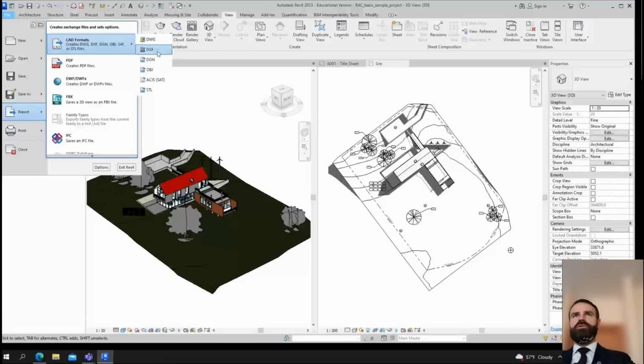If you open the same drawing as a DXF file in a text editor, you will see nice numbers and text, and you can modify data and get results. So practically you can create a drawing just by modifying text lines and the drawing will be changed.